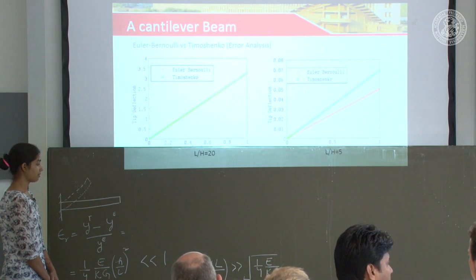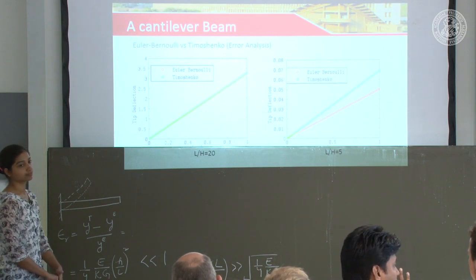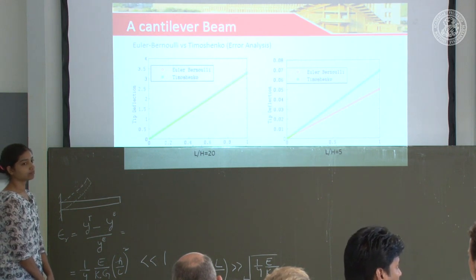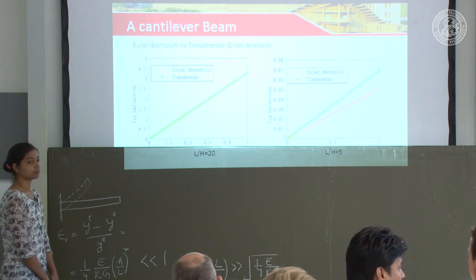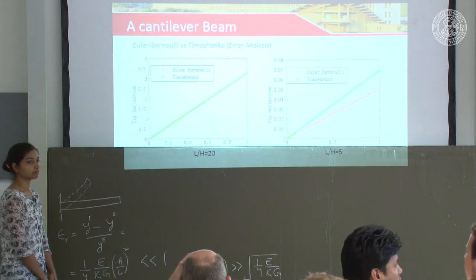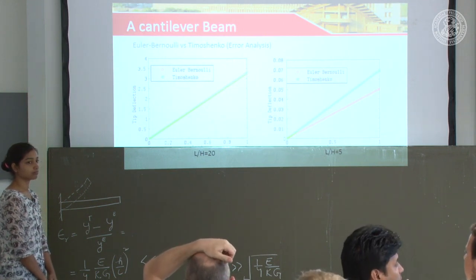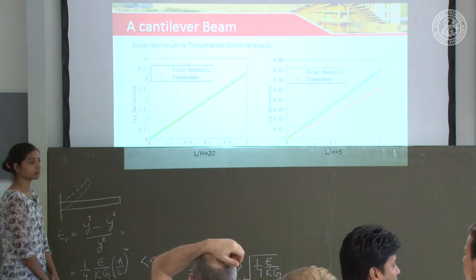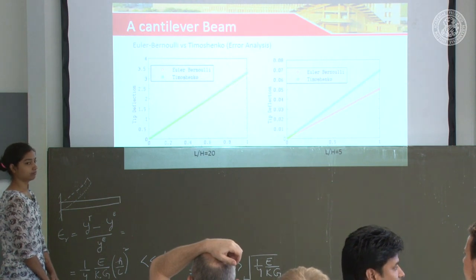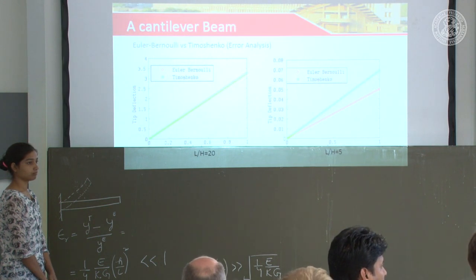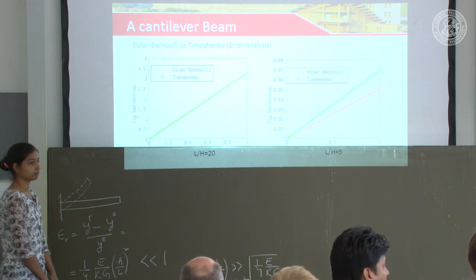Okay. So asymmetry of the cross section, I think that's what you're referring to, whether if the two moments of area are different, does that somehow affect this analysis? So that does not affect if you are restricting to one particular plane, then the other moment of area does not come in the picture. Only this factor kappa, which is actually coming from the shear sensitivity.